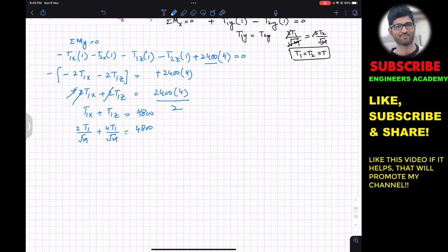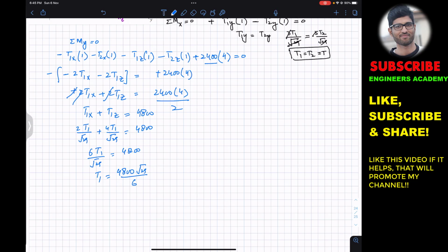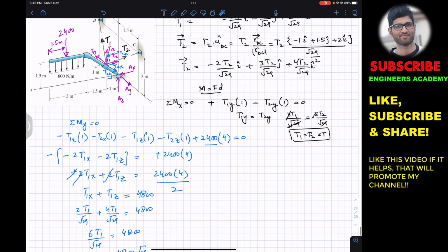Now we can add up both of these. So this will become 6t1 divided by square root 29 equals 4800, and from this we can say that t1 is 4800 multiplied by square root 29 divided by 6. This gives us t1 equal to 4308.13 newtons.